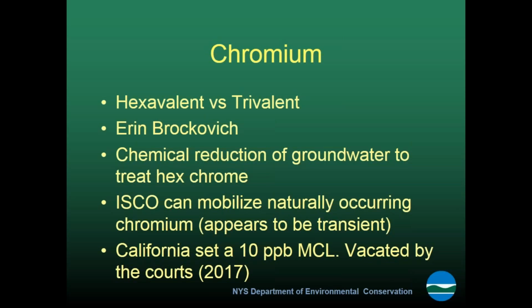New York was similarly looking at lowering their MCL at the same time, but in 2017, the courts vacated California's lowered MCL because they did not adequately take into consideration the economic cost of that lower MCL. When you start looking at how much chromium would cost to treat, it would be very expensive. And to my knowledge, New York is not looking at lowering their MCL at this time.